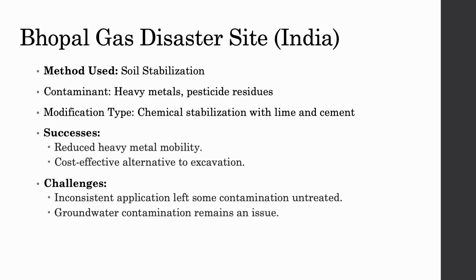So to address this, remediation teams turned to soil stabilization. They used lime and cement to chemically bond with the metals and reduce their ability to dissolve and move. And this worked well in the zones that were treated thoroughly and was far less disruptive than digging everything up.